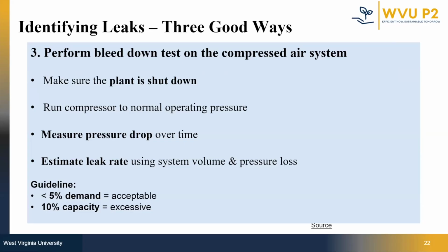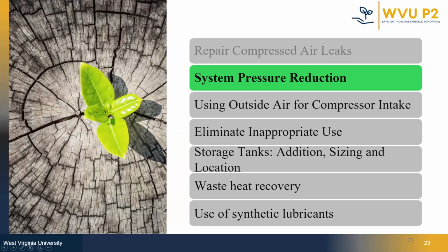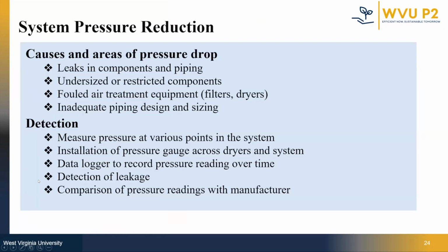If your leak is under 5% of the demand, that is generally accepted. But once you hit 10% or more, it is a red flag. It tells that the system is bleeding energy and money. Next, we have system pressure reduction.